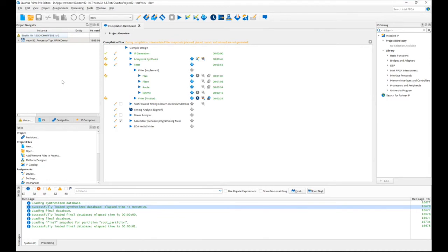What you're after in this particular case is the lab install, and what it will do is it will just download only the tools necessary to connect to your board to download the SOF file. So no, you don't need a full install of Quartus to be able to do that. That program or download also includes Signal Tap, if you're familiar with that tool. So you don't need a full installation to work with the design that includes the Signal Tap logic analyzer.